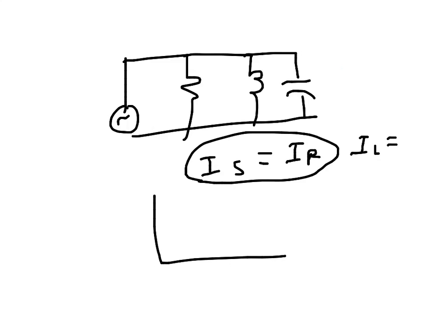So in resonance the current will be minimum. For the parallel resonance condition, the current will be minimum at the resonant frequency. So that's the thing. This is IS and that will be minimum. And also it's understandable from the 1 over Z thing.